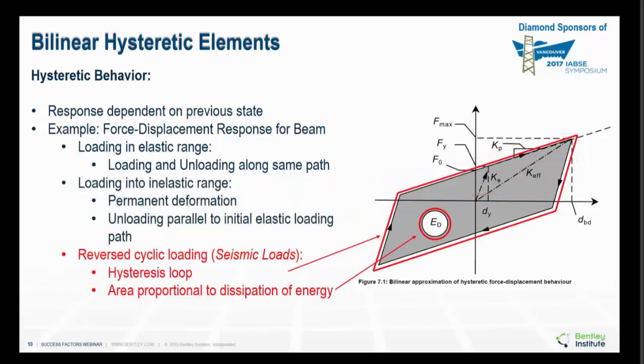In the cycling load, when we have a cycling load such as a seismic or earthquake, then we will have the full loading and unloading. As you see, we will have the hysteretic loop, and the area under this hysteretic loop is very important, which is related to dissipated energy by the element.